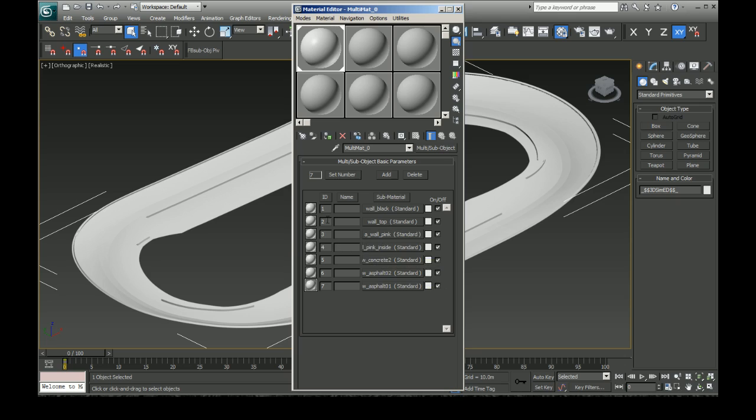And you can see here you've got the material IDs and the material subnames. These material subnames are still named .mip. Obviously 3ds Max can't handle .mip files. It can't display them in Windows. It's just not possible. What you can do is manually go through and change all of your MIP files in your TrackMap folder to .bmp files.